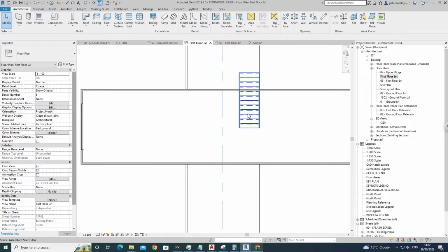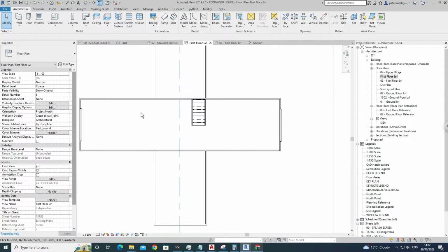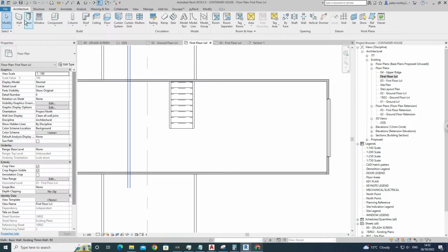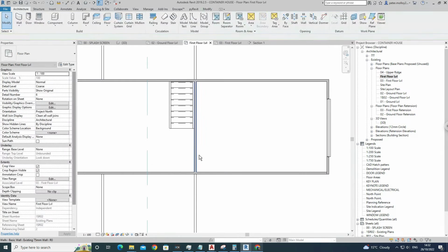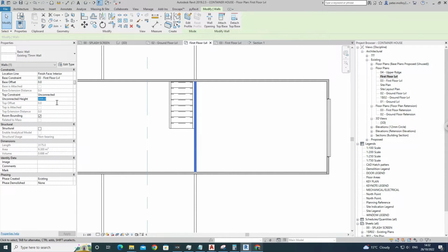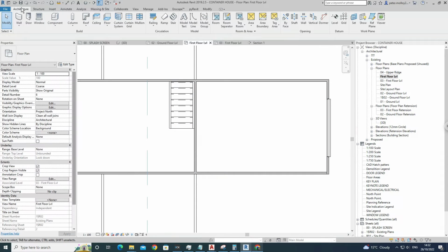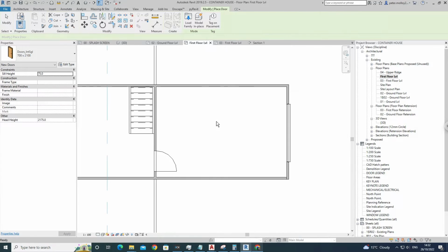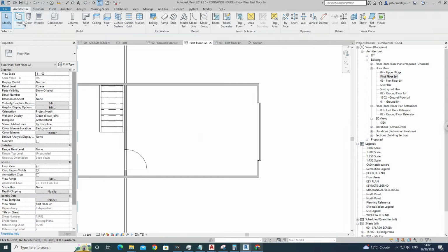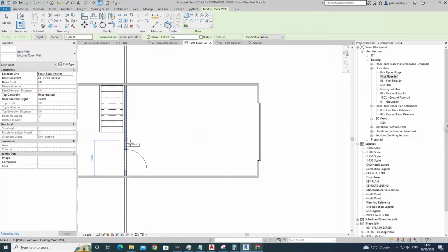What I'll do, I can use nearly all of this as, we'll just put a studio bedroom in the back along here. And 2600. Put a door in that. Remember to put them at 75, just because we're dealing with a 75mm tolerance for the floor.